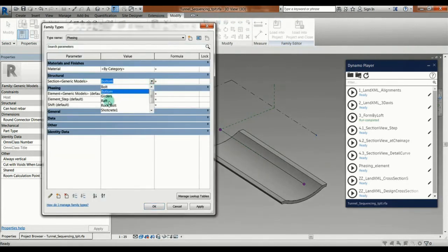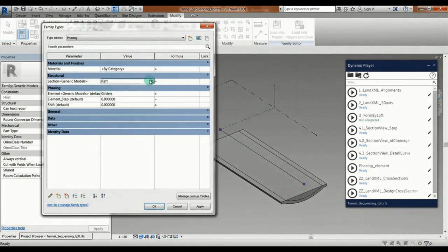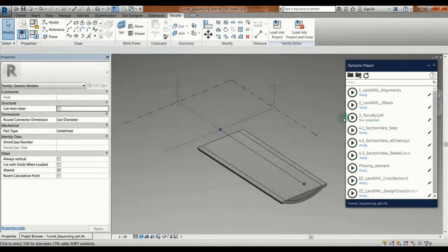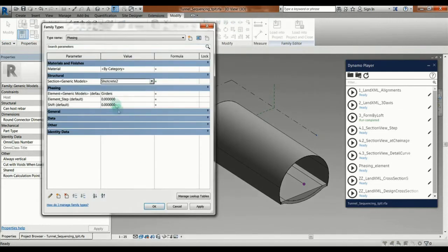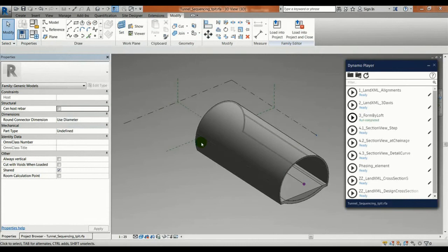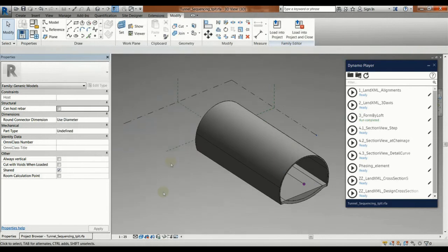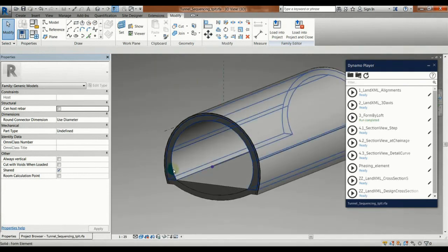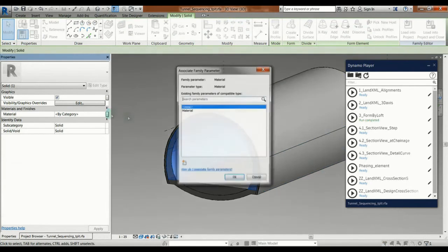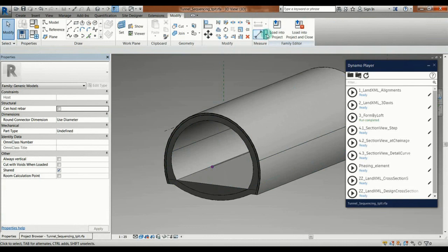I will do another piece of concrete here. Then the shotcrete layer 1 for the excavation construction. The shotcrete layer 2, and also the lining, the final lining. So I created each solid per phases. Okay, you will know why just right after. And then I can add some material for each solid because each shotcrete is cast in place, or depending on the concrete, you can add the material you want for every solid.